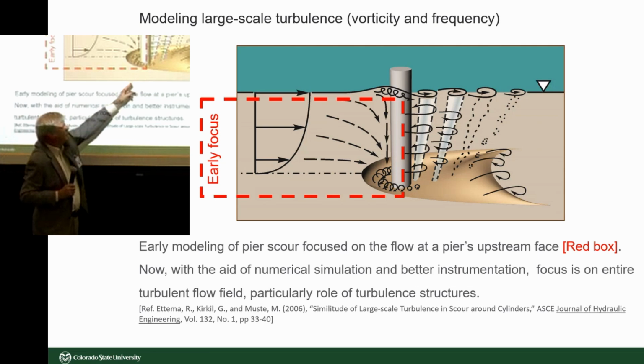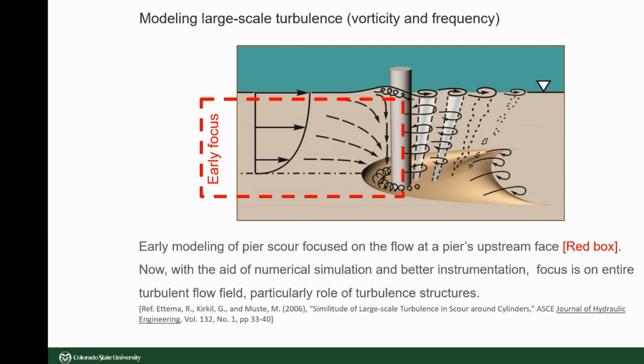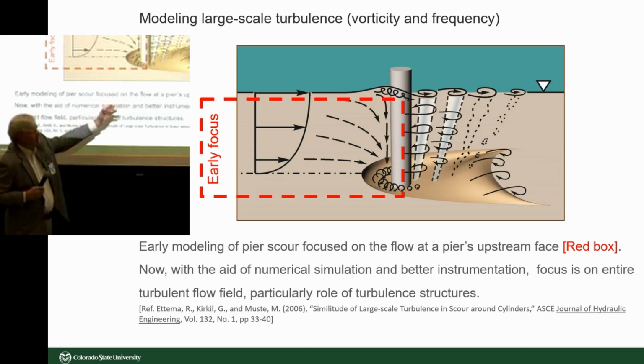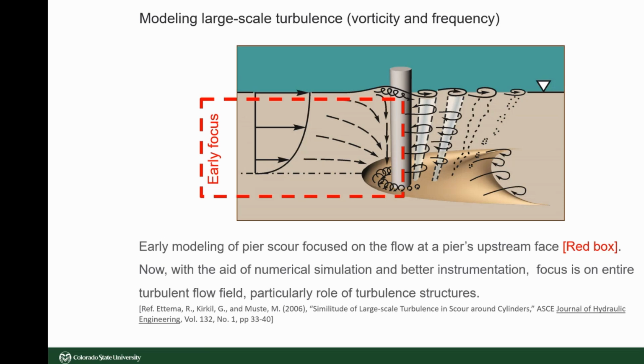And the good thing about this, no matter what the material is, whether it's sand, snow, the scour depth typically is at most in the lab about 2.3 times the diameter. That's the rule of thumb that I often use. It doesn't matter whether you use snow or rock. If you snowshoe through here and look at scour around pine trees, you never see a scour depth greater than twice the diameter of the pine tree. So no matter how complicated the flow field is, the scour depth doesn't change, provided you've got uniform material.